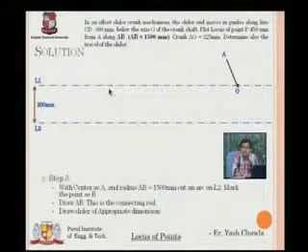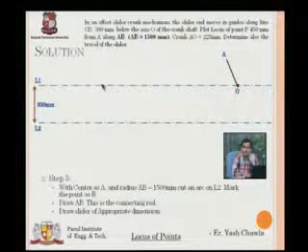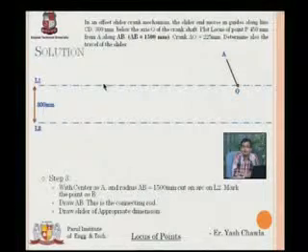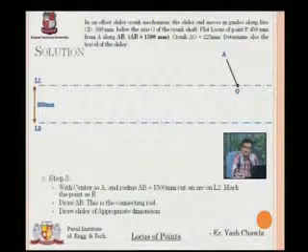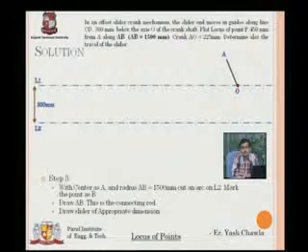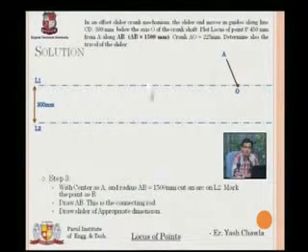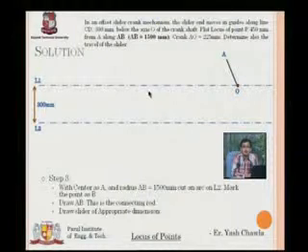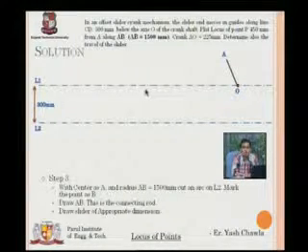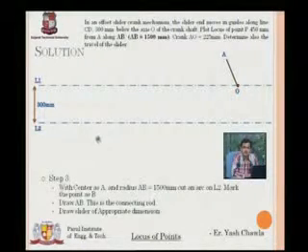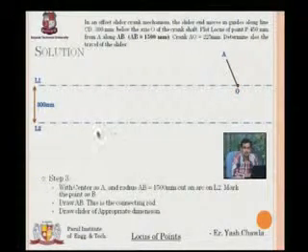That's why we took the radius equal to the connecting rod and cut an arc on the line on which both the things were oscillating and rotating. Between that problem and this problem, there is only one difference. Instead of cutting the arc on line L1, we are going to cut the arc on line L2. Why? Because my slider will be reciprocating on line L2.